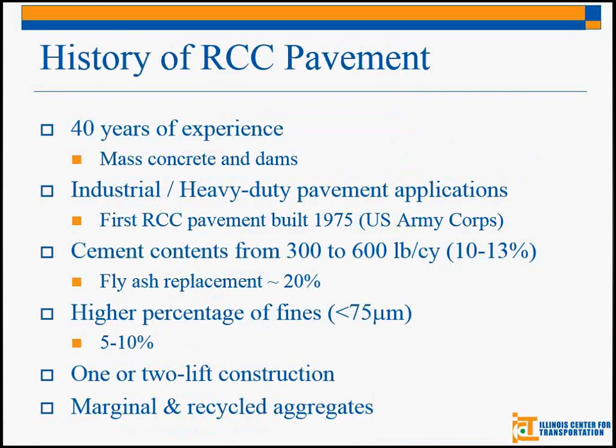So going into a history of RCC, it's not a new thing. It's been around for quite a while, mainly in dams and other mass concrete applications. As a pavement, it's typically used in industrial or heavy-duty applications. Typically, it's not a very pretty or aesthetically pleasing surface, so it hasn't really been used as a pavement very much. But the first actual pavement was built, as it says, in 1975 by the Army Corps of Engineers, and